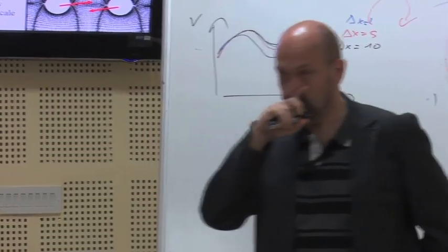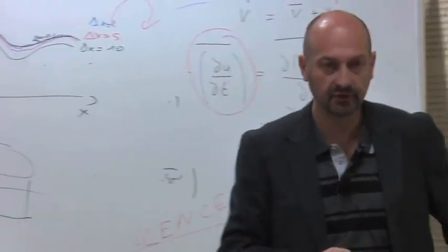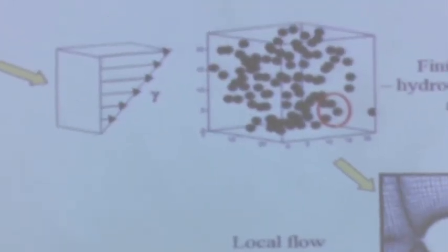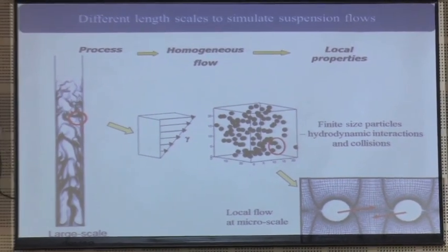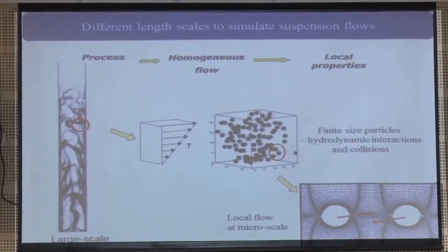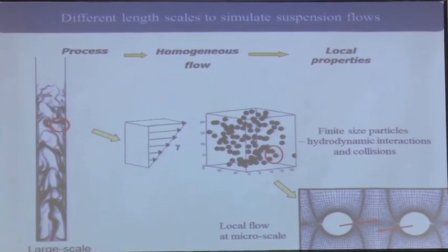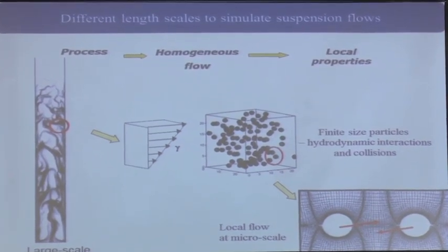Okay, so when you do CFD of multi-phase flows, you are facing new problems, which are very similar to turbulence. The new problems are coming from the size and the time scales. So you have seen that in turbulence, what is difficult is to simulate the whole domain, the size of the container, and the small scales.